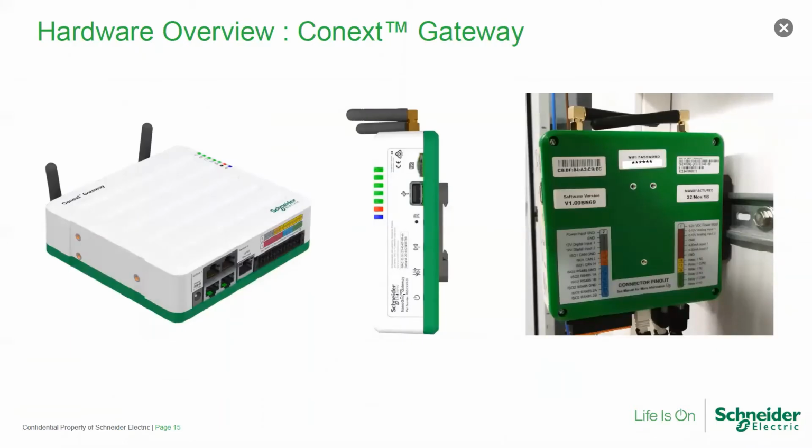So we can see here the back of the gateway. When you get your gateway out of the packaging, you will see that there is a label that has the Wi-Fi password of the unit. That Wi-Fi password refers to the access point that the unit broadcasts for a point-to-point connection with your laptop. So you can connect to the interface and log into the web server inside the unit and do all the programming of the unit, right? That password comes set up from the factory.